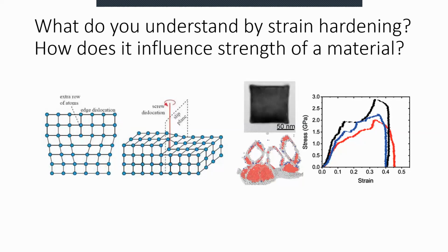This is due to an edge dislocation. Now, when you're applying force, there are numerous such dislocations present in a particular material. These dislocations keep on piling over one another. One dislocation comes, then another comes at the back of it, then another, and this keeps piling up, and this finally resists the movement of these dislocations.